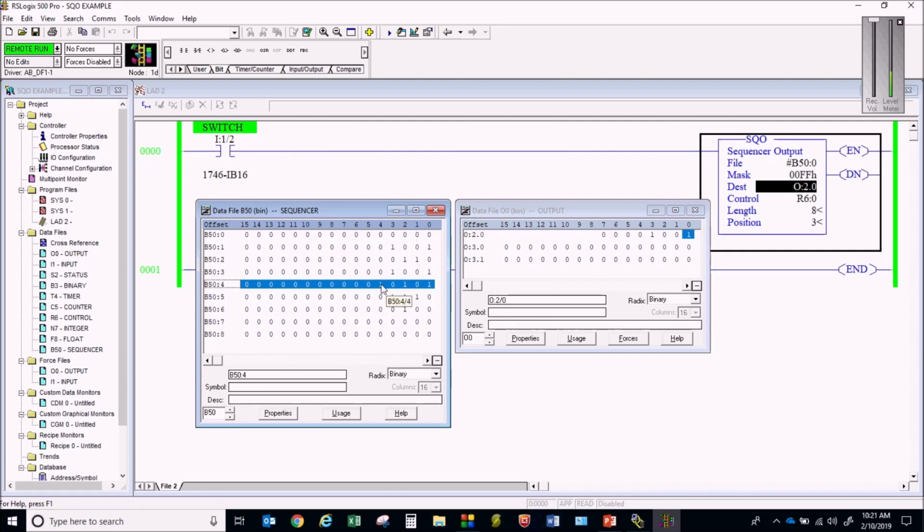Now this is the one that we didn't get this bit before. The reason why we didn't get this bit before was because we were masking to a 0 in that 5th bit. So we need to see if we get that 1, 0, 1, 0, 1. There it is. 1, 0, 1, 0, 1. The reason why is because we have that extra F in here now. And I wouldn't have had to do an F. I could have done just that 1 bit if I wanted to.